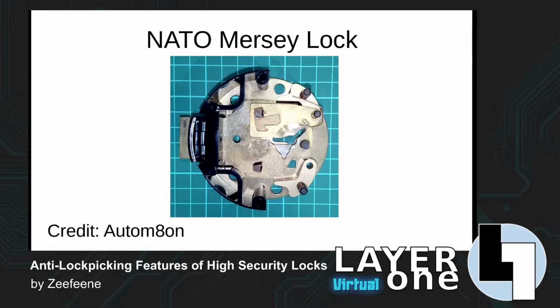And so when you attempt to tension the lock in the open direction, what you find very quickly is none of the levers are binding up, and instead you are basically just blocking the bolt with these two noses, which makes this lock phenomenally difficult to pick.